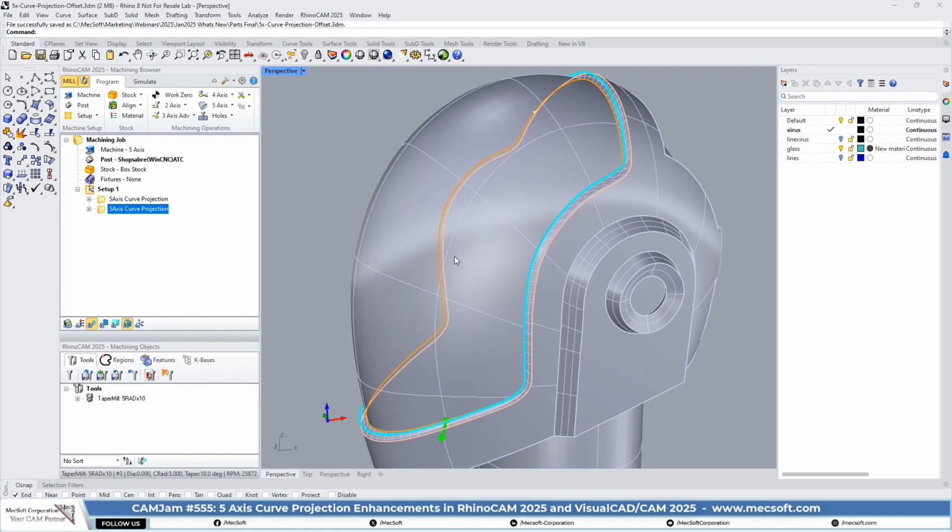In a lot of cases in 5-axis, you're cutting complex geometry, and also you may be cutting edges off of a part. So just think of if you have a formed shell on a car body, just an example. You punch that car body, you have a blank, and you're punching the shape in the car body, but you need to trim out the edges of it. Well, you can use a 5-axis toolpath.